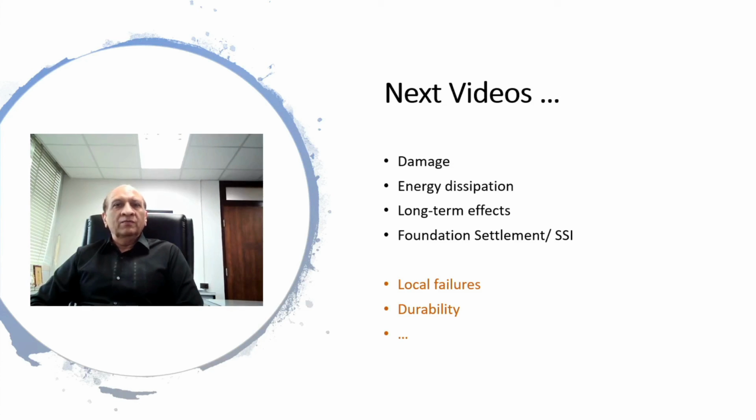For example, we will look at the damage due to repeated loading. We will look at energy dissipation because of the cyclic loading, seismic loading, and so on. We will look at the long-term effects of creep and shrinkage, and also we will look at foundation settlement, soil structure interaction, etc. So with these, we will probably cover most of the effects that we can model.